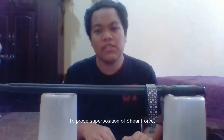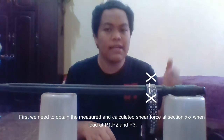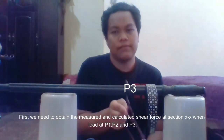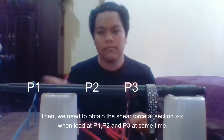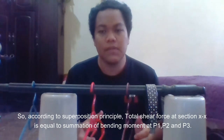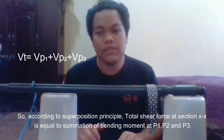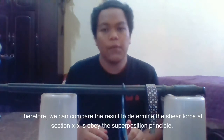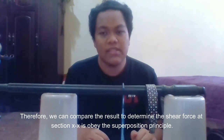To prove the superposition of shear force, first we need to obtain the measured and calculated shear force at section XX when the load is at point 1, point 2, and point 3. Then we need to obtain the shear force at section XX when the load is at point 1, point 2, and point 3 at the same time. According to the superposition principle, the total shear force at section XX is equal to the summation of shear force at point 1, point 2, and point 3. Therefore, we can compare the result to determine whether the shear force at section XX obeyed the superposition principle.